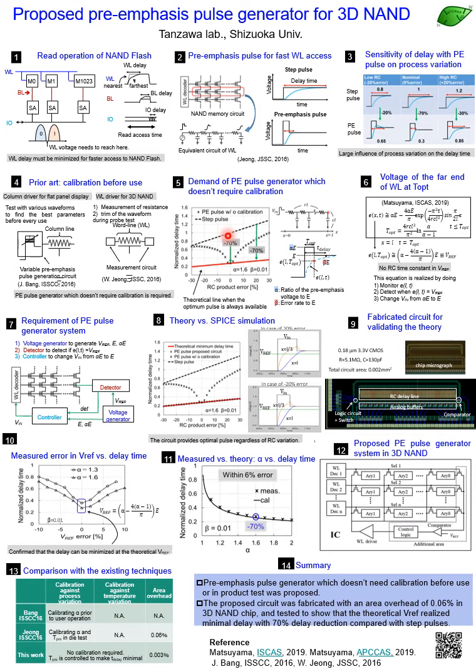When your pre-emphasis pulse width is fixed at the value for when the RC value is just the target value, then if your word line RC varies by some amount, the improvement in the delay time could reduce like this.